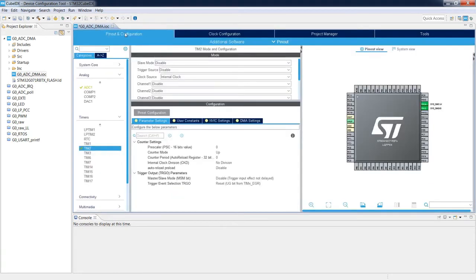Let's come back to the pinout configuration, and we've got a few possibilities here. I would propose the following technique. Let's use a Prescaler, which is a 16-bit value, to divide the clock as a first step. So I would propose to divide it by 16,000. It is important to put here the desired value minus 1, due to the fact that in the final calculation there is one added to the value stored in this PSC part of the register. After this operation, we will have as input clock to the timer, to its counter, 1 kHz.